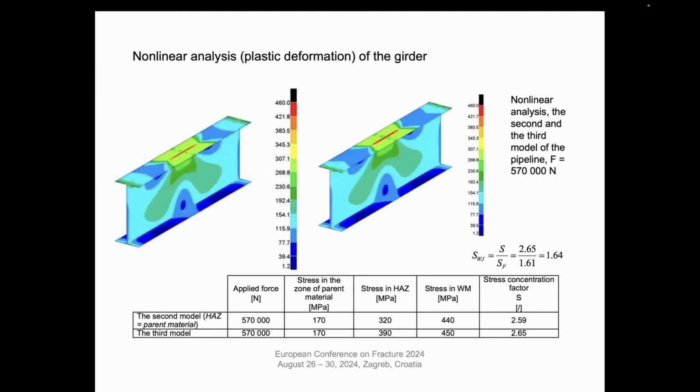Is the stress concentration factor actually the number that compares those two structures? When you look carefully and closely, you can see that the stress gradient is completely different in those two structures. So maximum stress is not the only thing that should be compared.